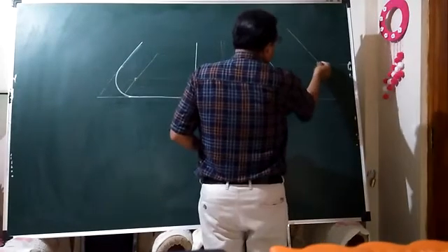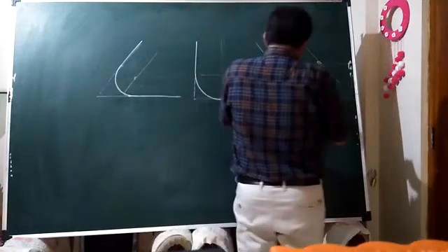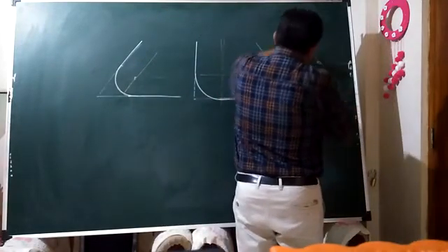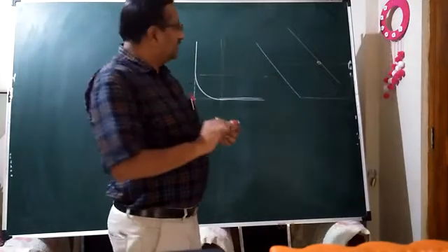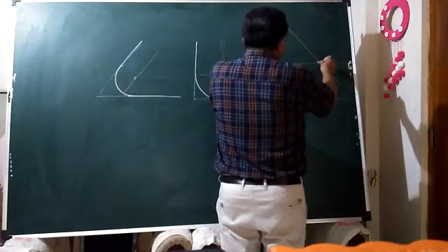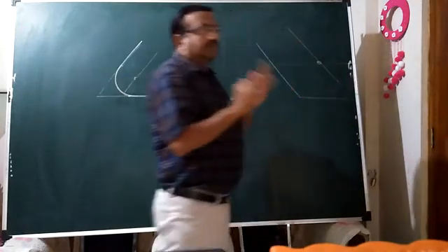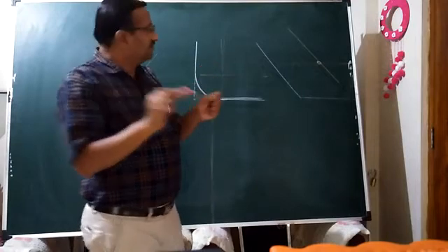So this will be the intersecting point. By the same intersecting point, don't pick this distance in the compass. Only and only the 50 mm distance of that curvature radius you have to pick. Don't make the mistake of picking this distance. You should pick blindly the given radius of that curvature, that is 50 mm.